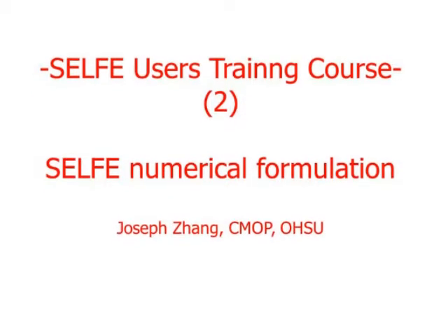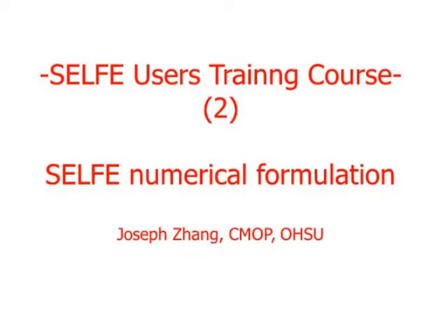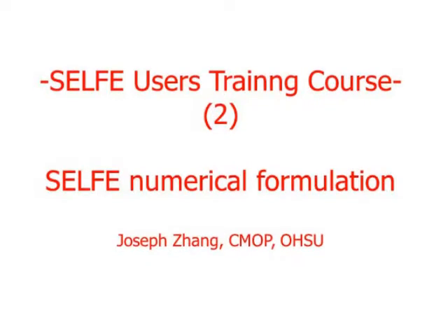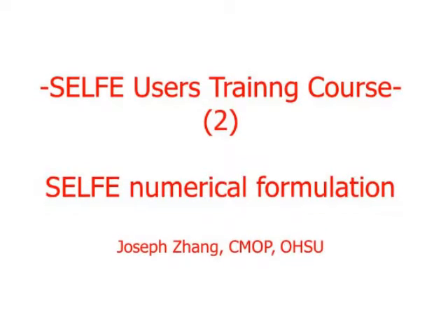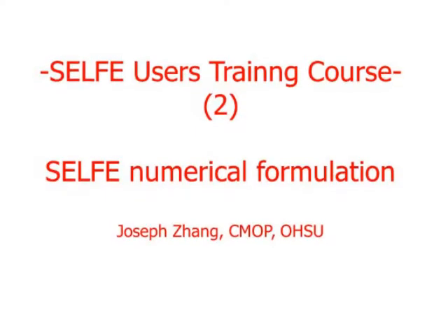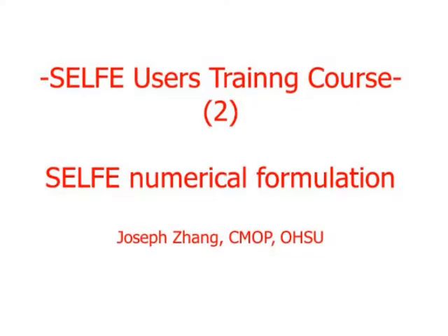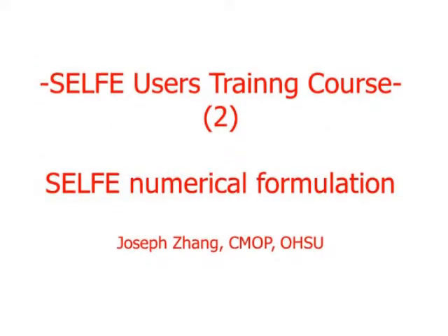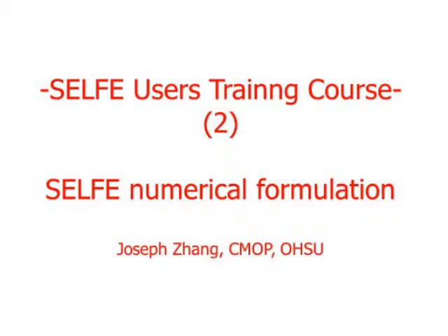So we are essentially taking advantage of so-called Eulerian-Lagrangian methods. This goes back to the pros and cons of Lagrangian and Eulerian methods. Eulerian methods, of course, are fixed in space, very easy to interpolate, and the derivatives are usually much easier to evaluate. But the drawback of the pure Eulerian method is that it usually comes with a severe stability constraint. Whereas Lagrangian methods do not have that severe stability constraint.